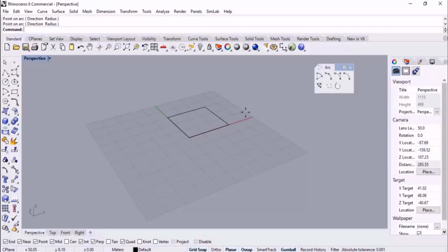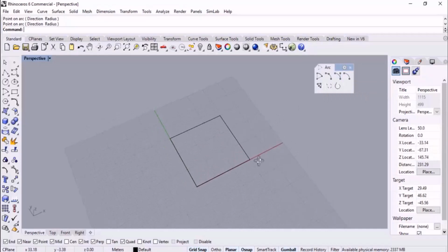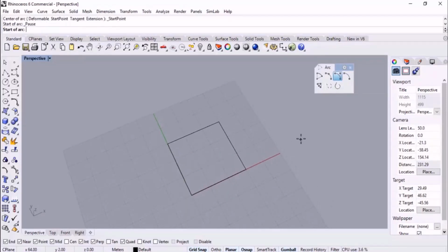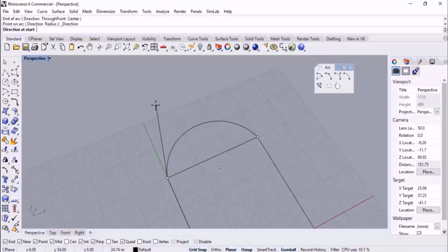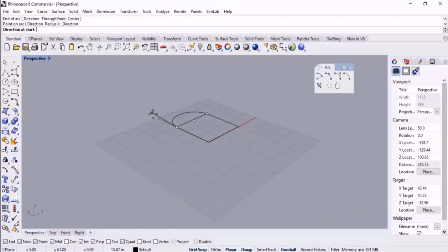What about the second solution or approach, which is using arc by start and direction at the start, or direction arc? Let's check it out, which has a point that I want to tell you, so watch this part carefully. Since it has an asset in comparison with others, we can sketch it by the start and then the direction at the start, like this. We can control the curviness, or the amount of curving. But here, if I hold down Shift in order to restrict the direction, then we can have the semicircle exactly.